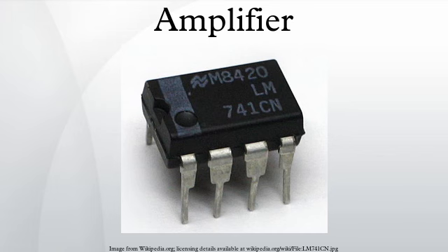A special type of amplifier, originally used in analog computers, is widely used in measuring instruments for signal processing, and many other uses. These are called operational amplifiers or op-amps. The operational name is because this type of amplifier can be used in circuits that perform mathematical algorithmic functions, or operations, on input signals to obtain specific types of output signals. Modern op-amps are usually provided as integrated circuits, rather than constructed from discrete components. A typical modern op-amp has differential inputs and one output.